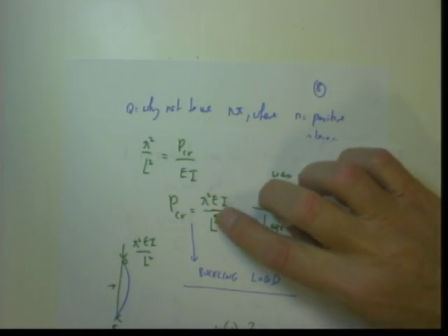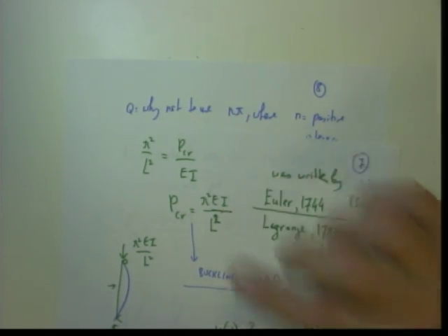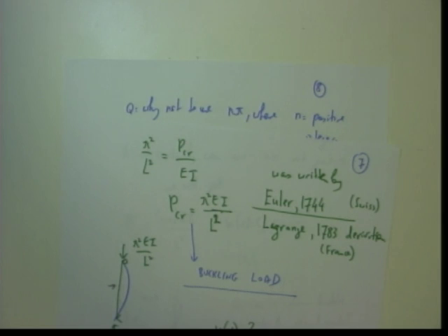Naturally, at this load there is a big displacement. Big displacement means that the differential equations that I wrote may be inapplicable, because they were good for small deflections. So all these conclusions are really in error, because mathematics is a model, naturally. Mathematics does not always describe exactly the world as it is. I have to use some differential equation. I used a linear differential equation, but the displacement is big. So that may mean that my differential equation